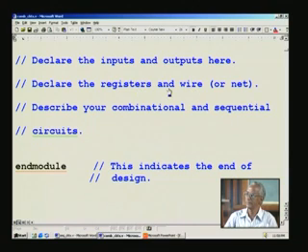What they are we will see after a few minutes, and they are basically signals used in always blocks for registers, and assign statements etc. will be wire or net. We will go into a little more detail a little later. And then you follow with your actual code, and what we have already covered earlier in combinational and sequential circuits was precisely belonging to this category.